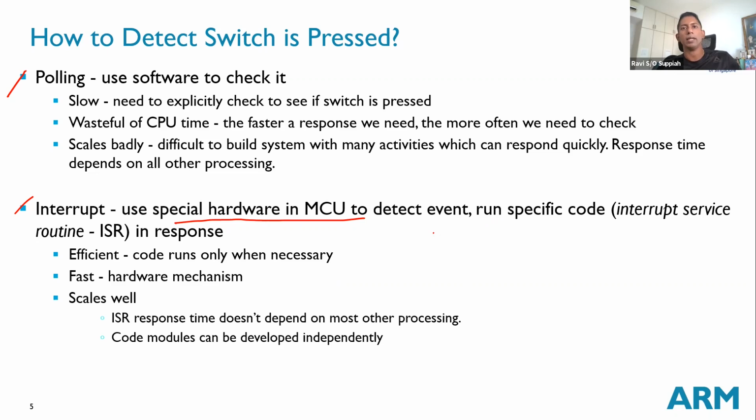Of course, it is very efficient because it is only activated when the event happens, so it's also very fast. It scales well in the sense that it allows you to add more real-time response capabilities to the system, but as always, you are limited by what the hardware offers. If your controller only has maybe 3 or 4 pins that can have GPIO interrupts, then you are limited by that. So the limitation is in the hardware, but it does give you a lot of efficiency when you want to quickly react to events.